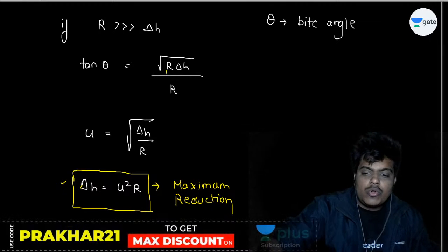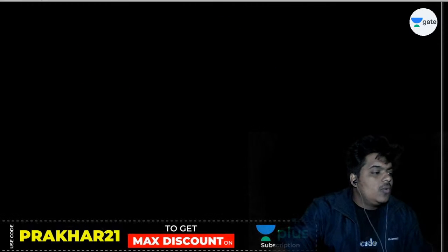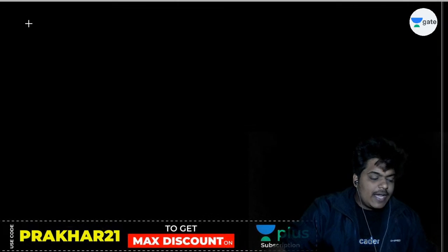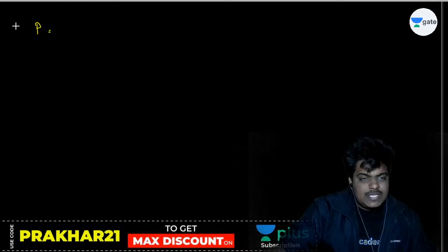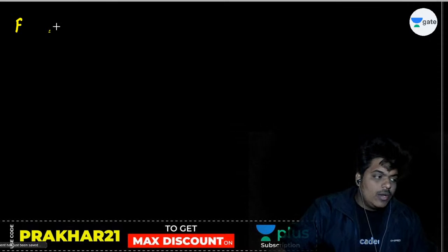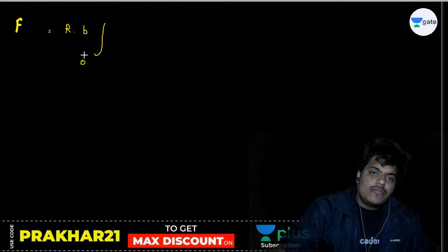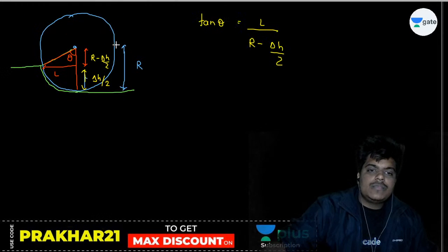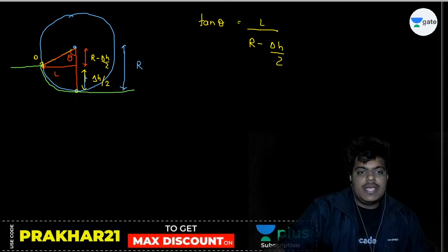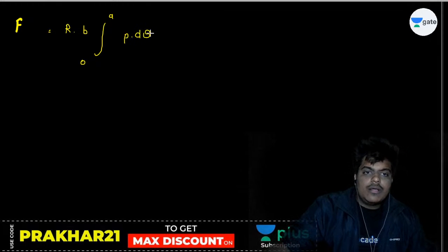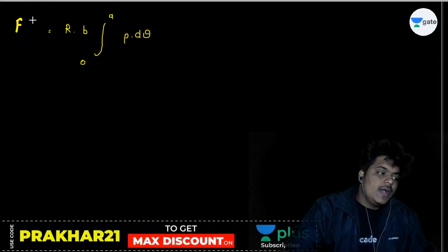Now if somebody asks you about rolling load, what will be the value of rolling load? Look, the simple concept of rolling load is this: this is not power, this is force. Rolling load is equal to radius into width into the integral from 0 to A of P dθ. This is 0, here it is A. Is it clear? This is the formula for force.